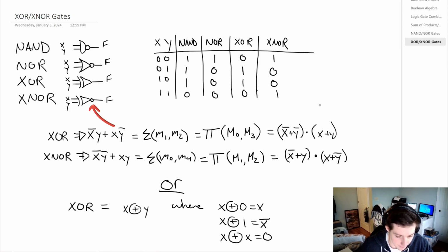on the output. And we know what the inputs and outputs are for the NAND gate and the NOR gate, as we talked about in the last video. But now we're going to define the outputs for the exclusive OR gate and the exclusive NOR gate. Now the exclusive OR gate operates on the basis of the output being high only when one of the inputs is high, which is similar to the OR gate, except in this case where X and Y are both high, we get a 0 for the exclusive OR gate. And then the exclusive NOR gate is just the inverted exclusive OR gate.